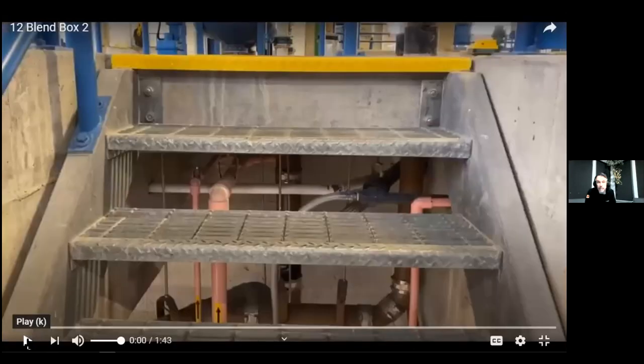So for us, we have water from a number of different sources. I take water from the creek and I take water from a lake and I blend it and I put the right amount of coagulant in, flash mix it, and I put it through those flocculation tanks. And you can see those big propellers that are in the tank. What's really important is that as the water moves to the next tank, the mixers are much slower.